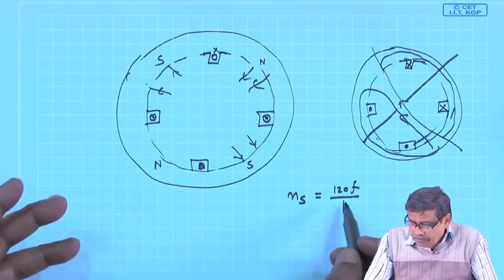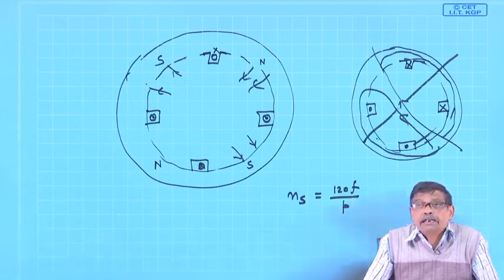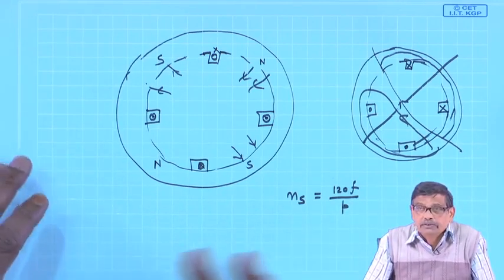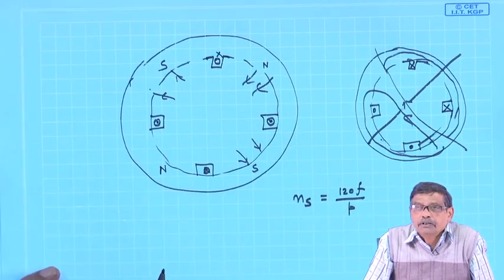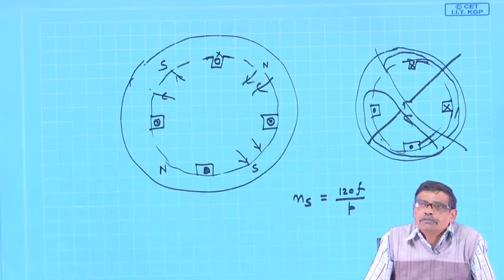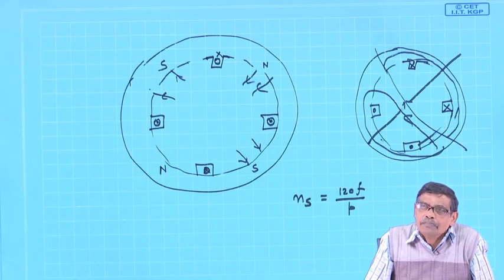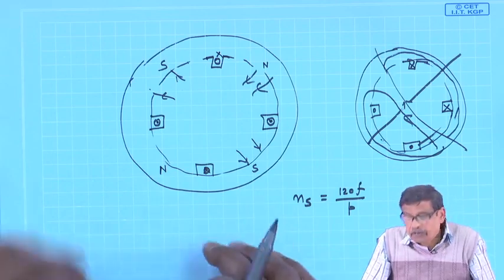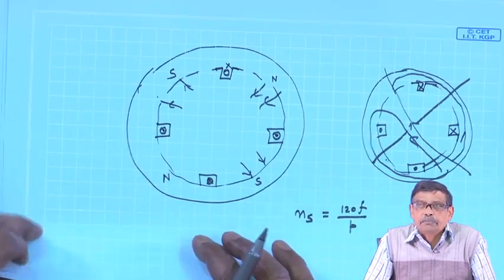So, people thought with the same windings whether p can be changed, hence Ns, and this cannot be done continuously. No continuous speed control is possible, only 2 discrete levels of speed you can have from the same induction motor. Anyway, we will continue our discussion from this point. Thank you.